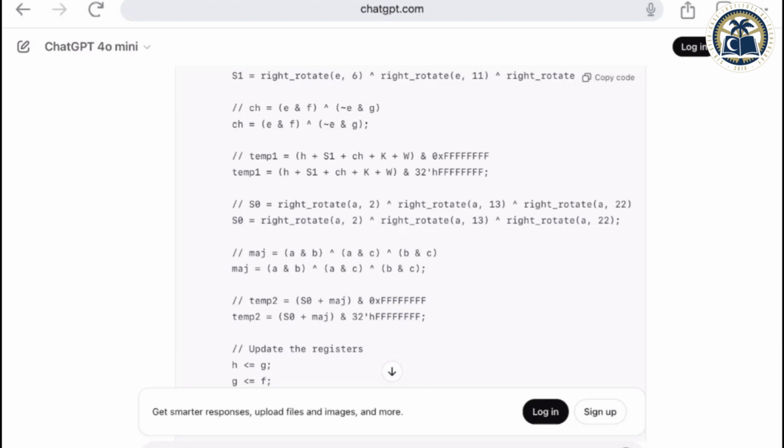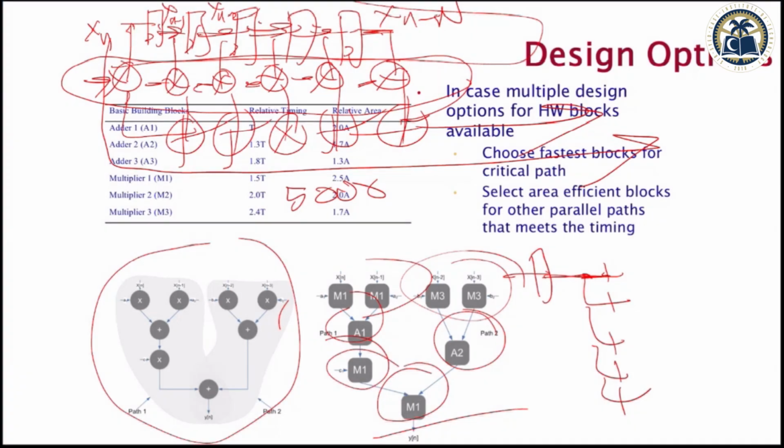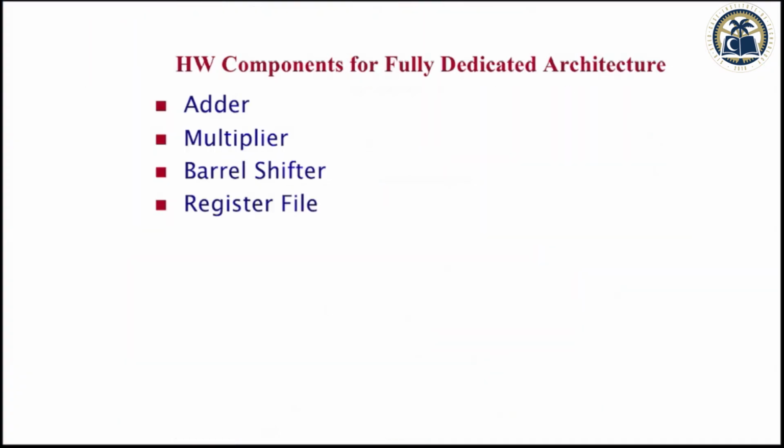The next iteration is expecting the computation coming out of this iteration. So you start getting questions: though I have a dedicated parallel architecture, what should I do to reduce the critical path of all these additions, where one feeds into another, then another? These are the things that require thinking, because one-to-one mapping is good, but sometimes in one-to-one mapping you will not meet the critical path.